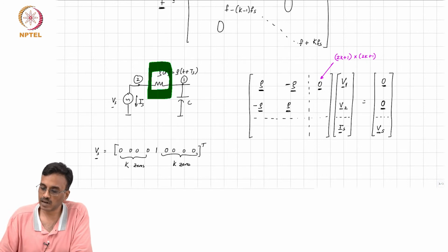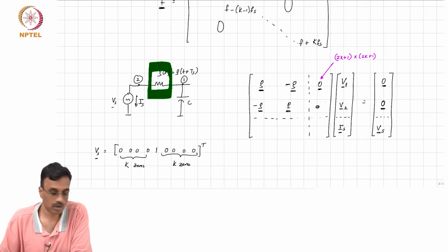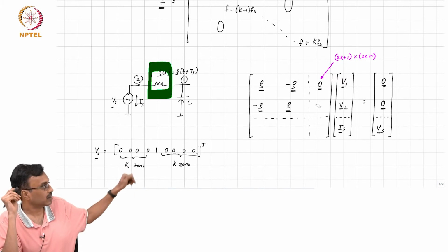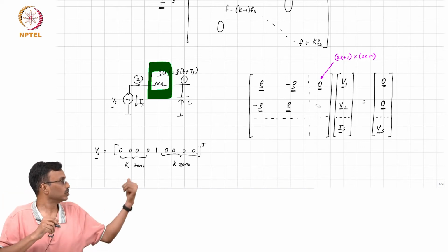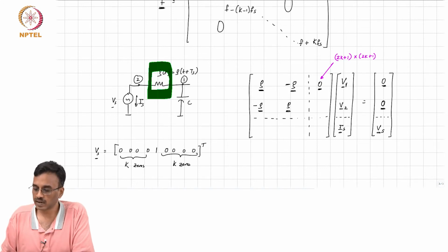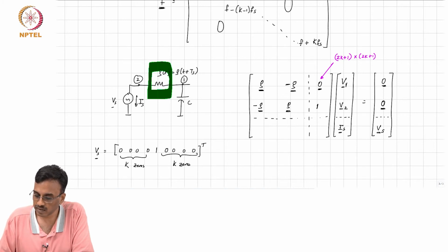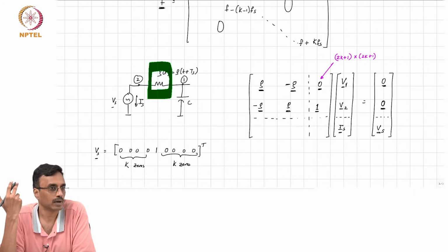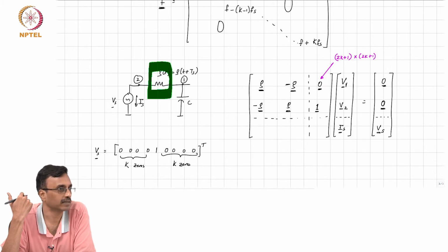Okay. And similarly, what comment can you make about second row, third column? Basically, the currents flowing through the voltage source basically must all add there, right. So, that must be the identity matrix. And what are the dimensions of that identity matrix? 2k plus 1 cross 2k plus 1. That makes sense.